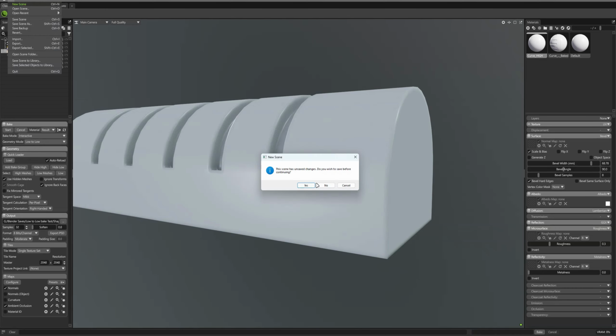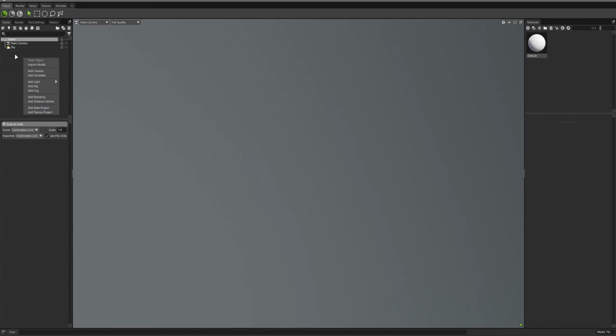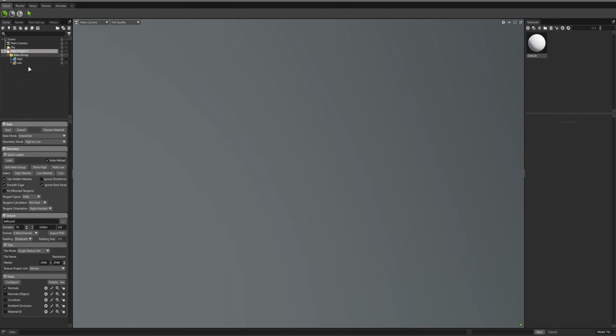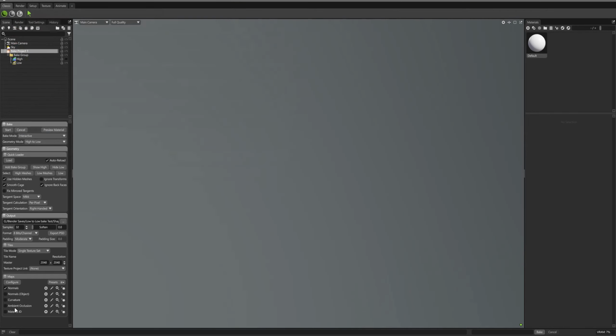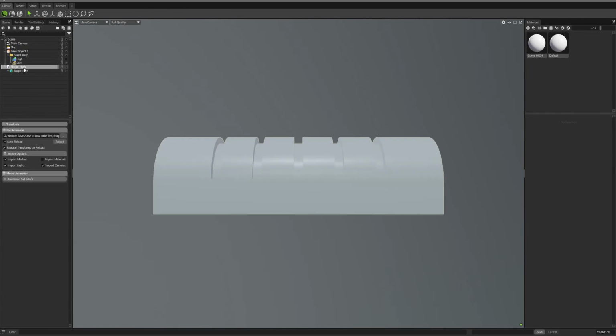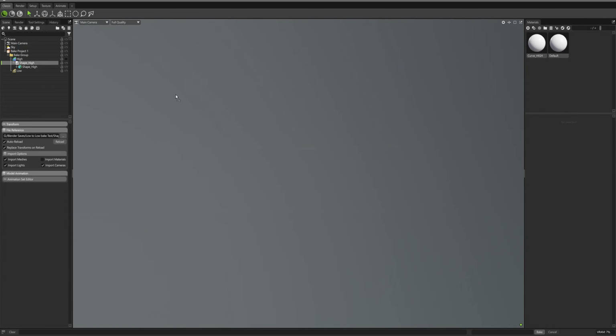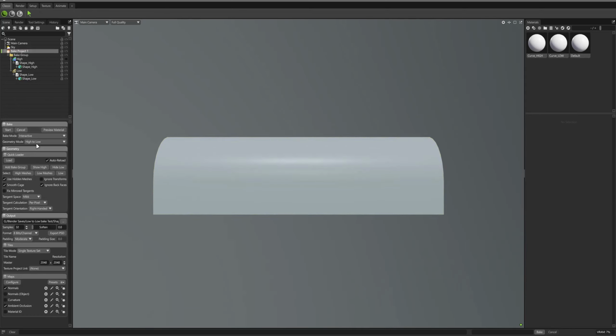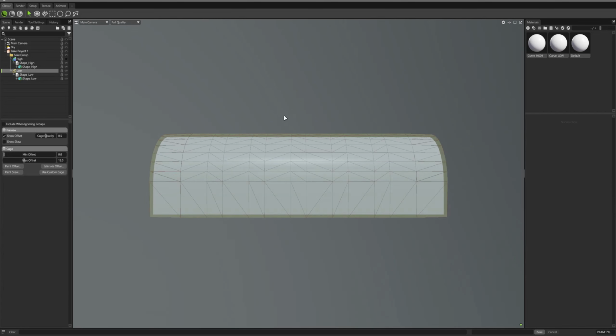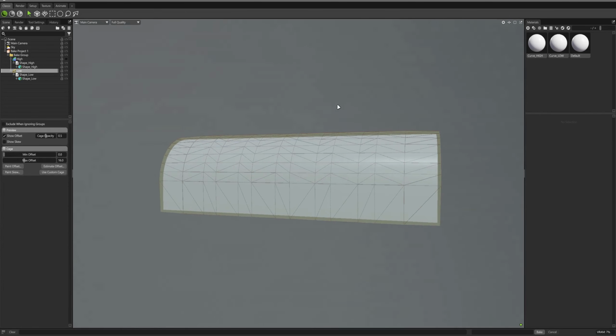What if this was a high to low poly baking, right? So I'm gonna add a bake project, and this time we're gonna use high to low. I'm gonna set my output maps to high to low. I'm gonna call this shape, Targa, up the samples. I'm gonna bake the ambient occlusion again this time, and I'm gonna bring my meshes, so high and low. There we go. And high to low set. If I take a look at my cage, it's fine.